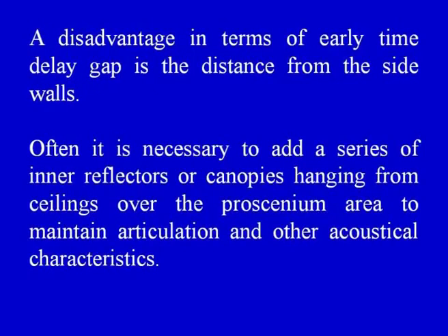A disadvantage in terms of early time delay gap is the distance from the side walls. Often it is necessary to add a series of inner reflectors or canopies hanging from the ceilings over the proscenium area to maintain articulation and other acoustical characteristics.